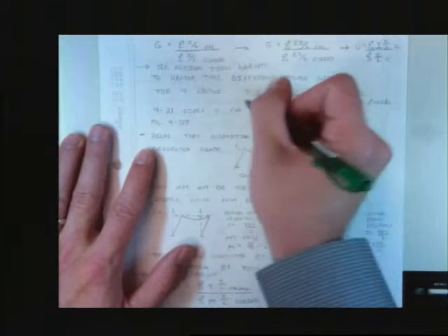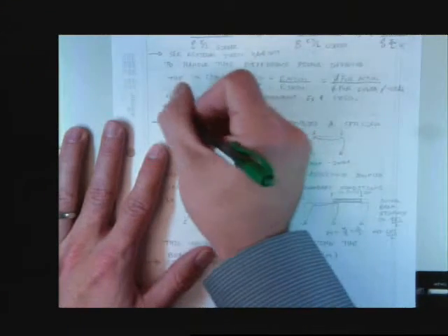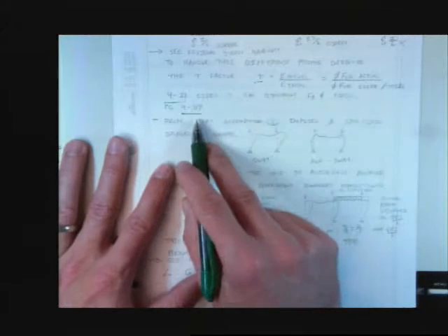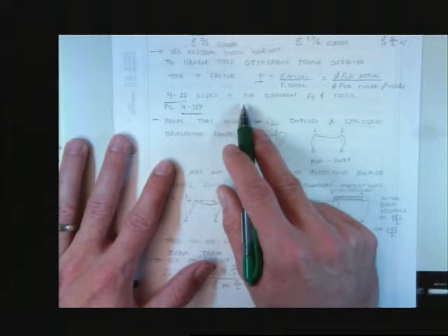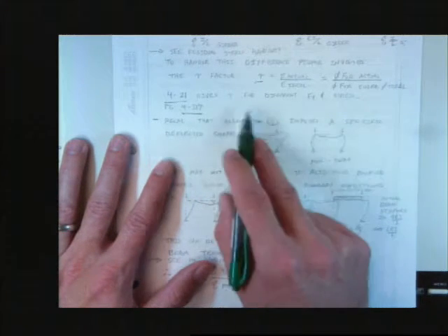Okay, and we're going to use the tau factor. There's a table in your manual, Table 4-21, and it used to be on page 4-317. I think it still is, but you should check it. It's close to that at least. It gives you the tau for different Fy and stresses. So this is pretty cool.